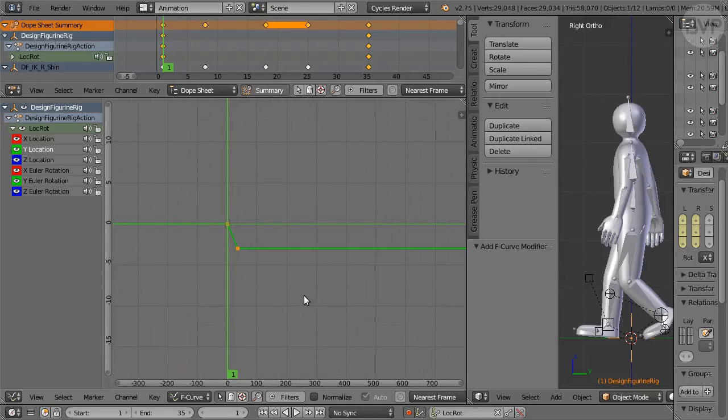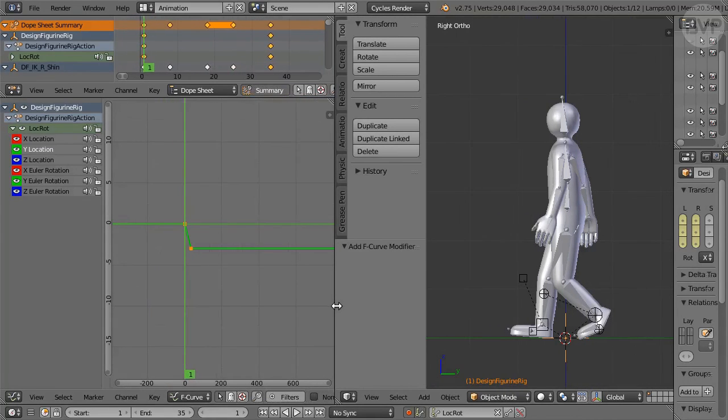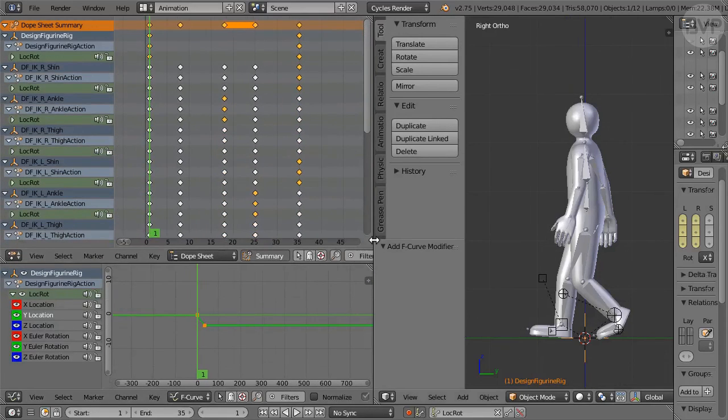The rig presently travels 3 units per cycle, so 3 times 3 is 9, and 35 frames times 3 is 105. However, Blender will remove the end frame from each cycle to keep the animation flowing smoothly. In 3 cycles, 2 frames will be removed. So the correct frame for the rig to stop moving is 103.